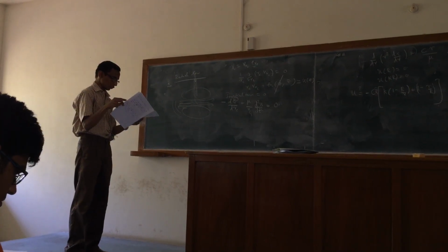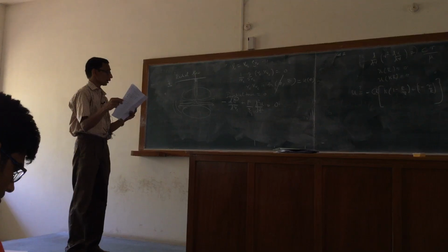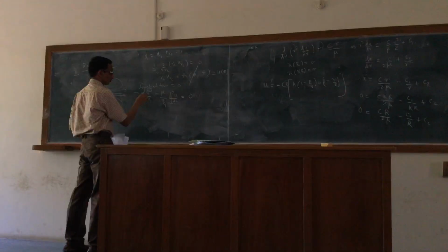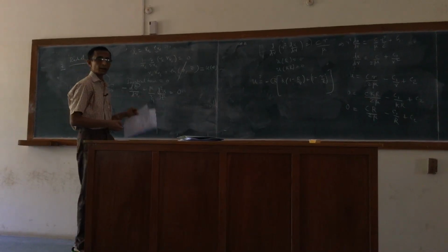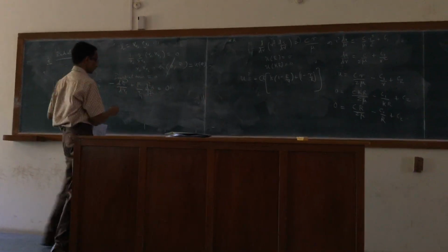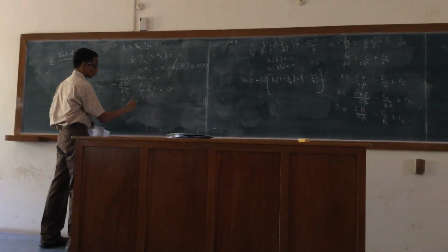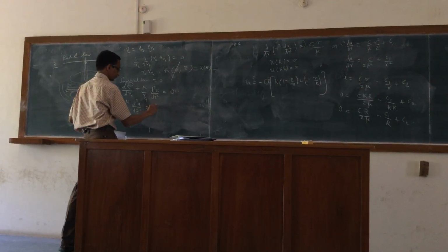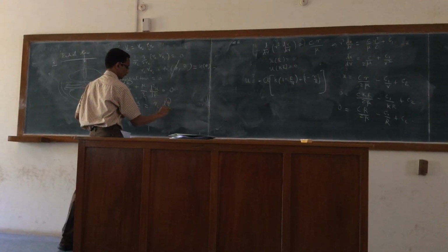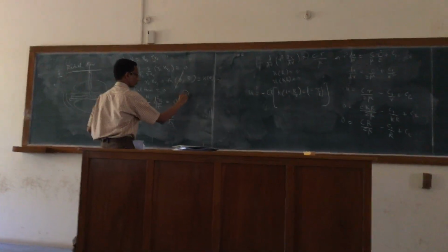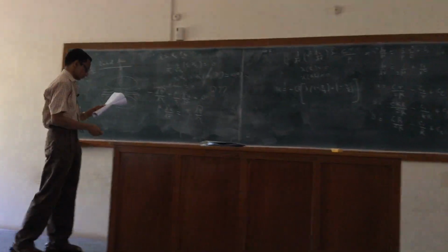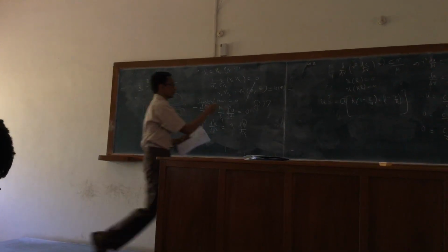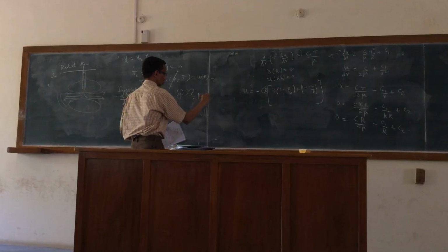So now the question is, how do we solve the equation? Clearly V will be a function of RC alone and U is a function of Z alone. So I can rewrite this as mu d squared U by dz squared is equal to RC dP by dRC. Now of course the question is, what is P here? P is actually P plus rho G Z.